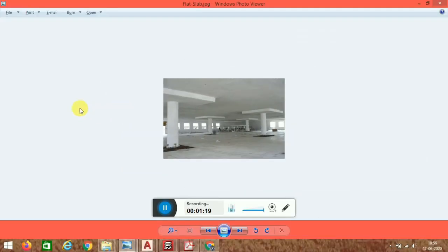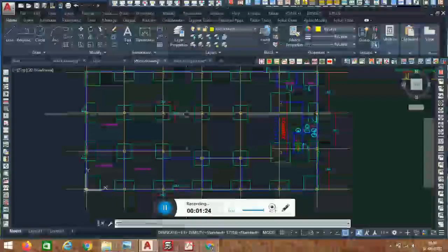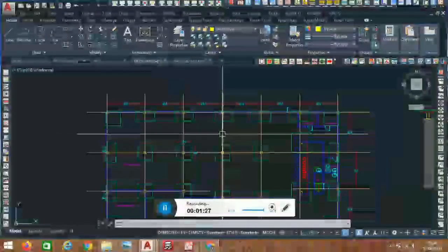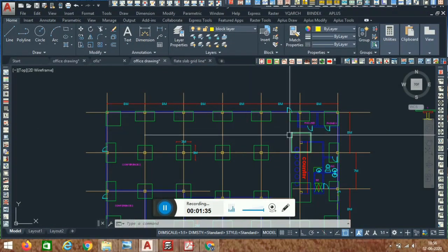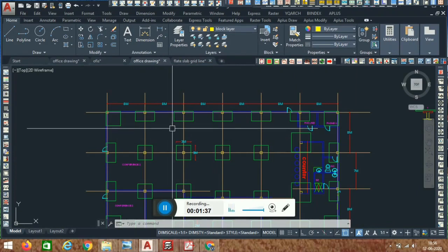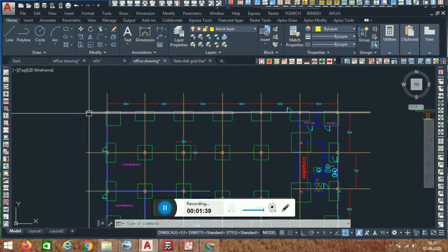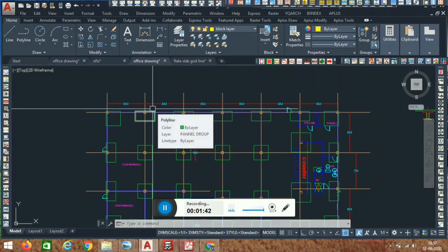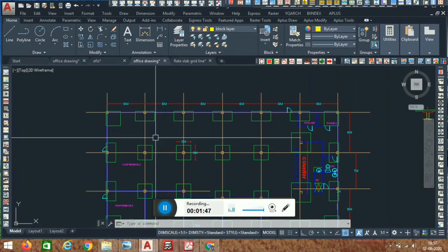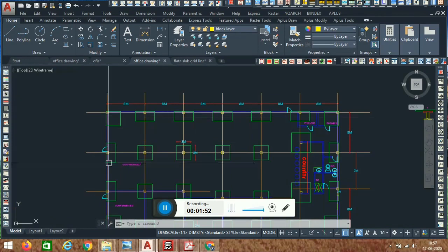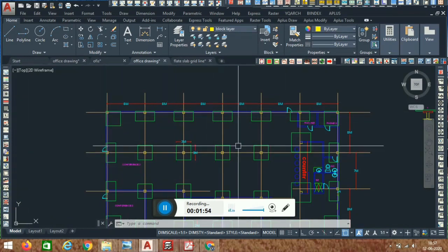So how can we do the design and analysis of a flat slab by using CYPE software? If you see the IS code 456-2000, on page numbers 53 and 54, we get the method and the requirements for the construction of the flat slab. And this is one of the powerful codes of the Indian standard. If you talk about the NBC, the Nepal standard, 205, on page numbers 25 and 26, we get some methods for the construction of the slab.